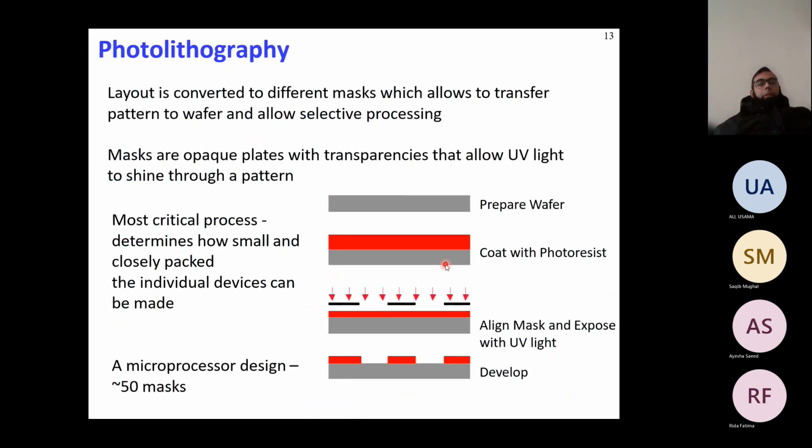Next, photolithography. Photolithography is basically patterning any kind of surface. Suppose you get a silicon wafer, and you want to deposit metal in some part, and you don't want to deposit metal in other parts. So you need to mask the area, right? The masking process is done using photolithography. There is something called a photoresist, which is sensitive to light, and we expose the photoresist through a certain mask, and that will form our pattern, like how you want to form your source drain, etc. Basically this is very crucial.